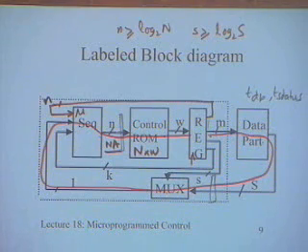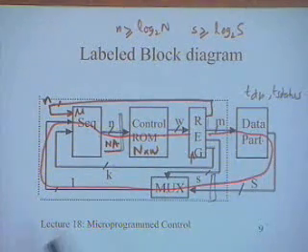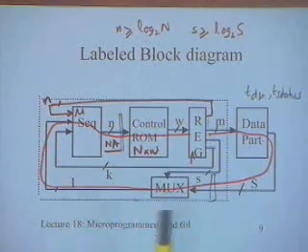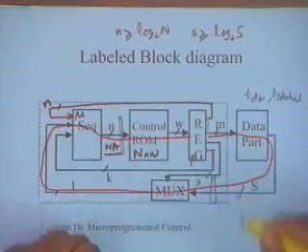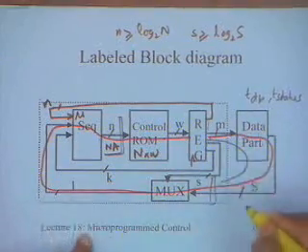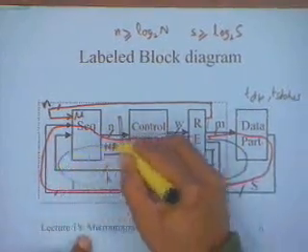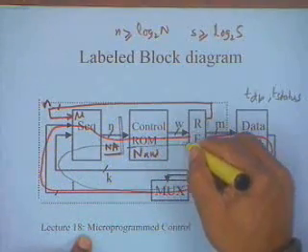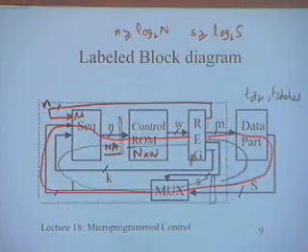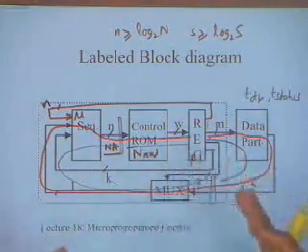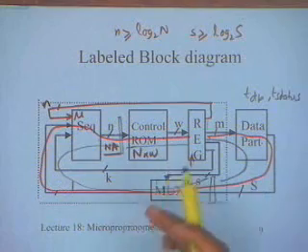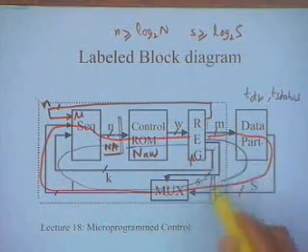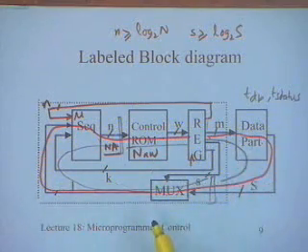What happens is once you put a register, this path gets broken. My definition of my clock period will be the maximum of this path, maximum of this path, and maximum of this path. I have split my path into 3 parts and I have to take the maximum, so I don't have to add these. Of course, small register delays will get added up in each of the paths, but still it is much less. So you can split it into 2 or 3 parts.